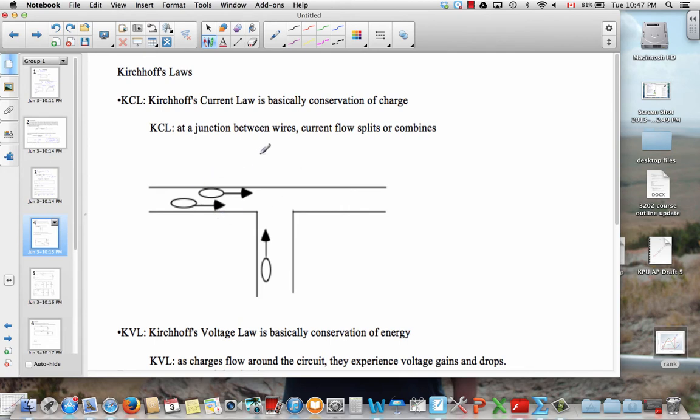really definitions. And then in terms of the concepts of circuit analysis, there's two, Kirchhoff's laws. First of all, KCL, the current law, basically says the charge doesn't appear or disappear. So for instance, if you've got a junction between two wires, then the amount of flow that's leaving the junction is the same as the amount that's flowing in. So at a junction, the sum of the currents in must equal the sum of the currents out.